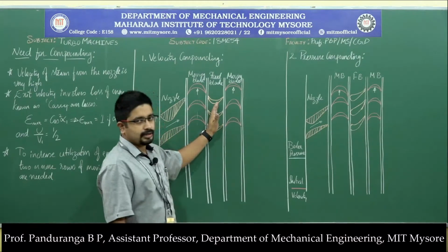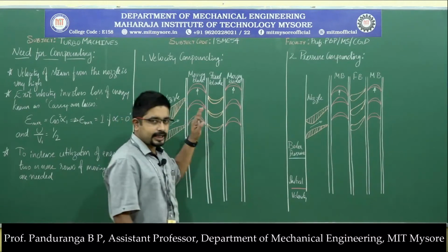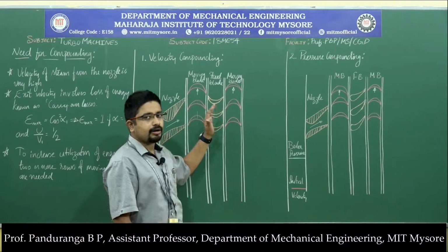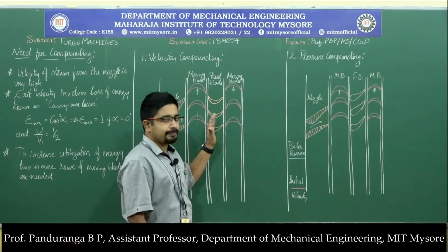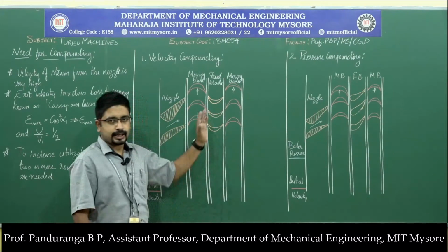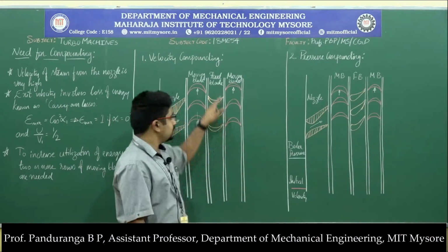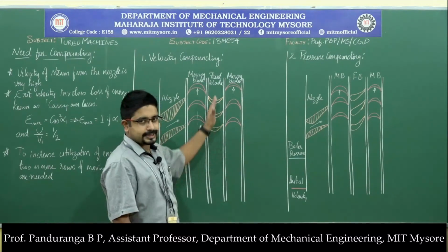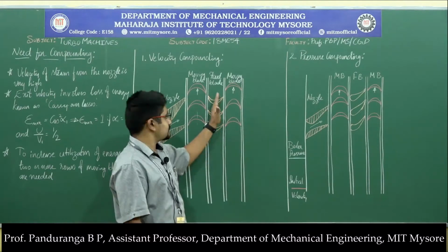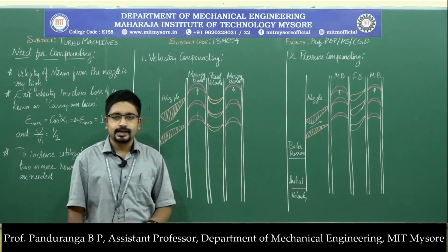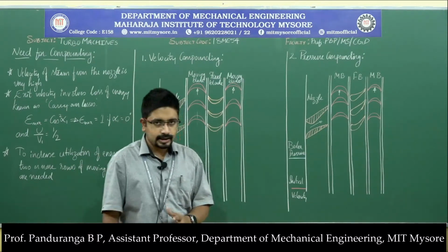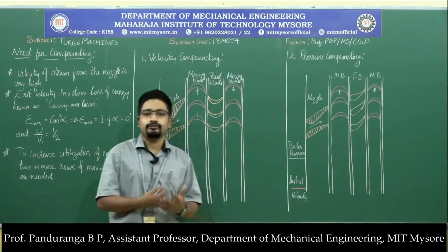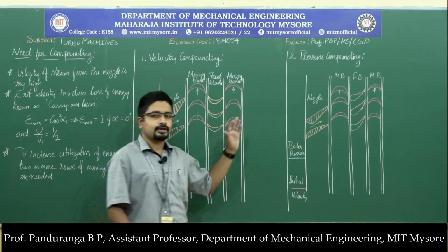Then we have the fixed blade. This is just to guide the steam to the next row of moving blade. So there is no change in pressure or velocity when the fluid passes over the fixed blade. Since there is no change in pressure, the fixed blades are also symmetric in structure. Since these blades are fixed, there is no motion of the blade, and since there is no movement of the blade, there is no work done. So the blades will not absorb any energy.